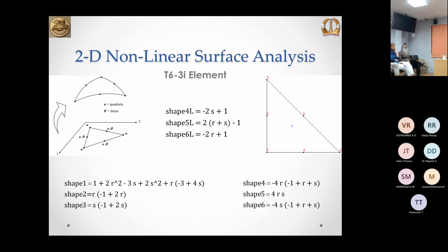Finally, I have to take that forward and do the 2D nonlinear surface analysis. For that, I need FEM elements. But the complexity is that I have rotations also and the displacement, so it's a 6 degree of freedom structure. Rotations are not so simple. These are the main culprits while updating the algorithm.